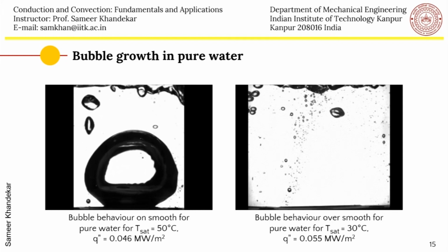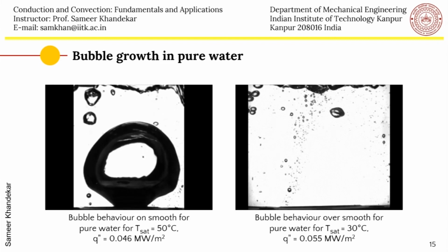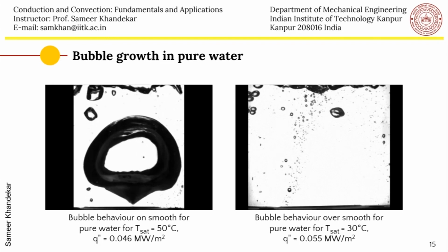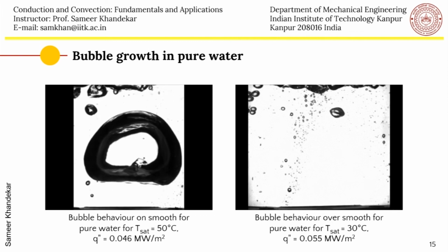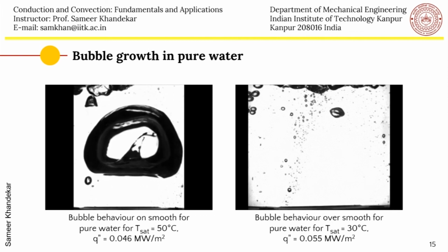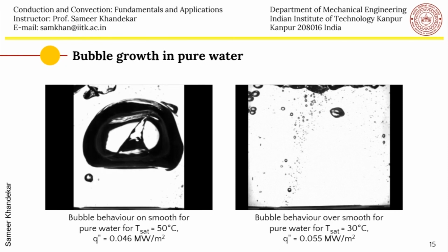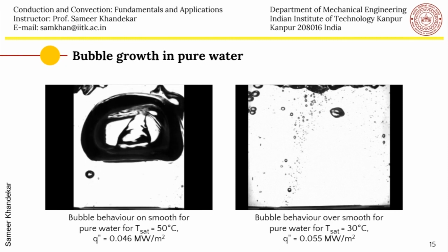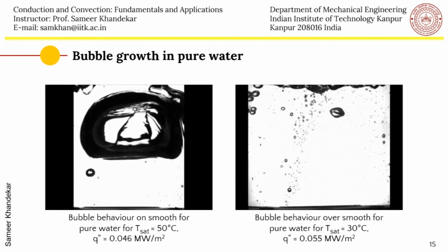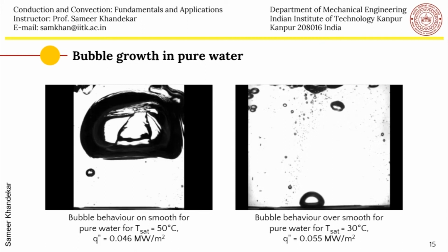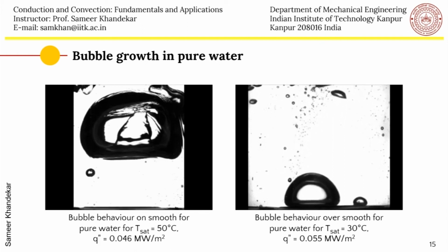Similarly, in the second video you can see another nucleation site, and then there are two sites now, in fact 3 or 4 smaller sites. Now the queue is slightly larger, and you can see more nucleation sites becoming active. There is also some merging taking place because of the interaction of the bubbles which are forming from nearby